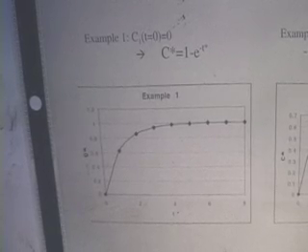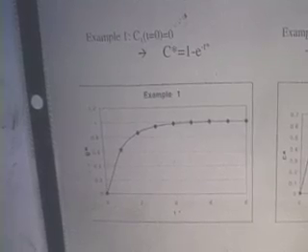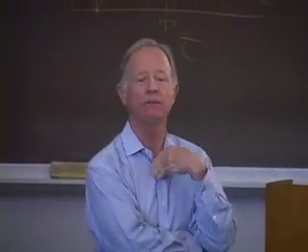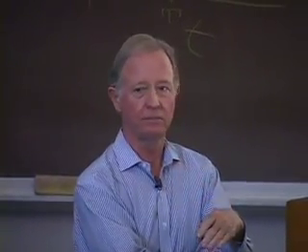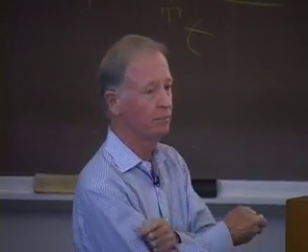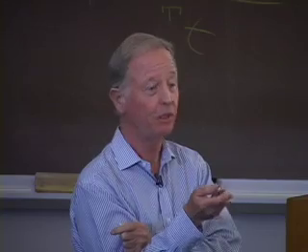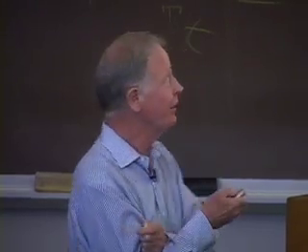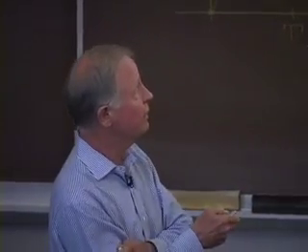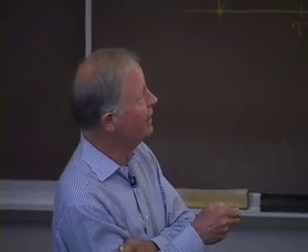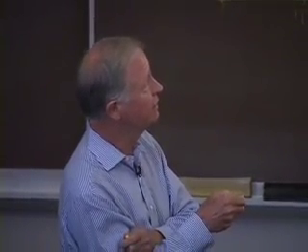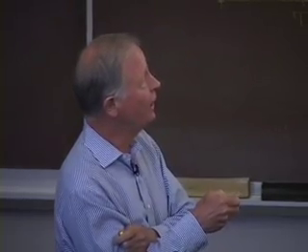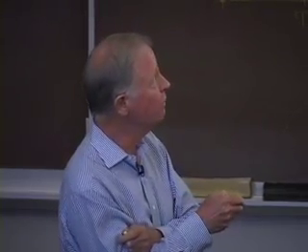Now, if I were to ask you, after 10 minutes, what is the concentration in the tank? What would you need from me to use this plot? You need the flow rate, the volume, all that. You have to ask me for V and Q because I need to put 10 minutes into T. I need to divide by the V over Q that I give you, which gives me a what?